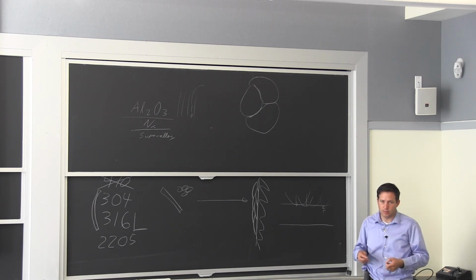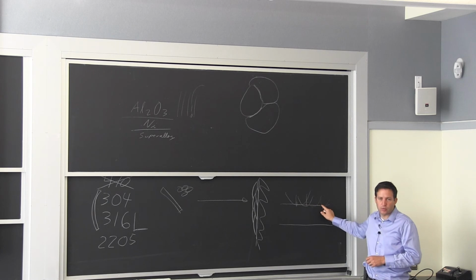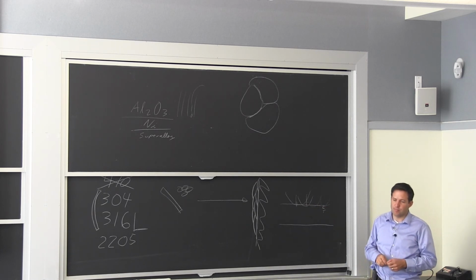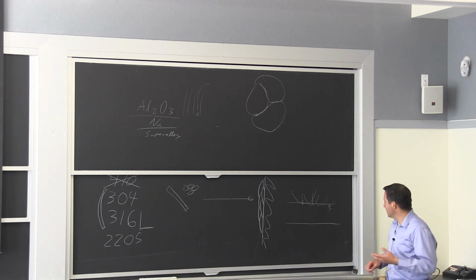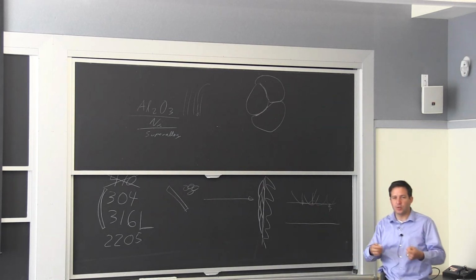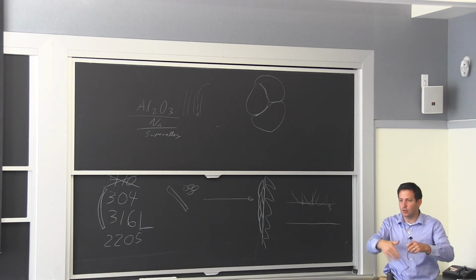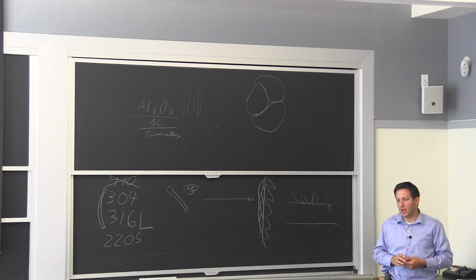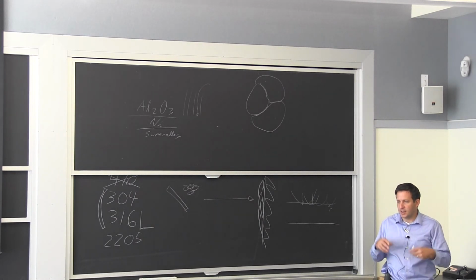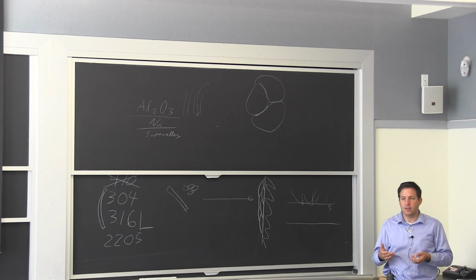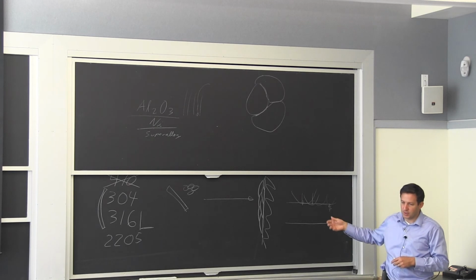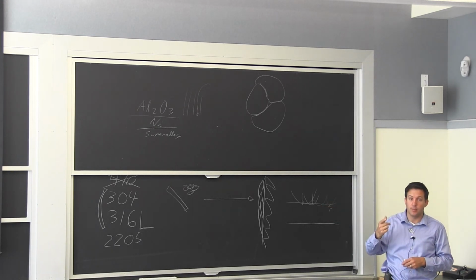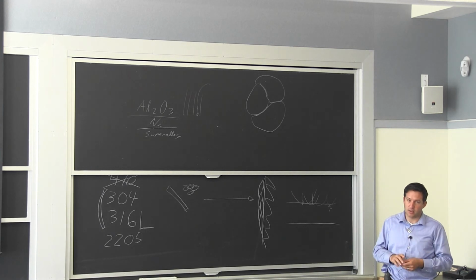If you have cyclic loads, you worry about forming cracks on the surface, so that's a way to minimize, if not eliminate, the crack initiation. It's not 100% reliable because there would be one area where the two beads coincide, or you at the corner, or you in a little radius, and that's why a lot of times it's an added benefit. It's delaying the crack initiation. But when we do this, a lot of times, in terms of design, we still consider, oh well, it may start cracking, and we're going to pick it up by inspection and replace that component.